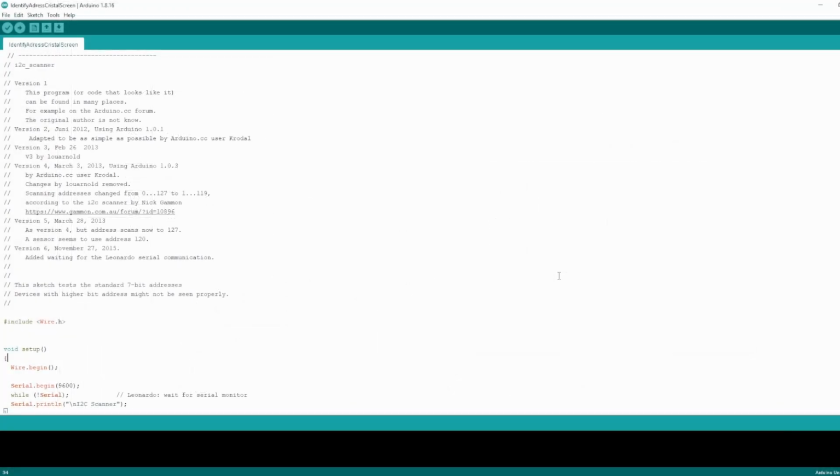Before I start working on the Arduino code, we first need to get the I2C address. When you are working with I2C modules for your Arduino projects, sometimes the manufacturer doesn't give the address of the I2C device inside the chip. It can be a serious problem if the address is unknown or you write the wrong address. The scanner will cycle through all the possible I2C addresses, and once it receives a response from the device, it will inform you of the address to work with.